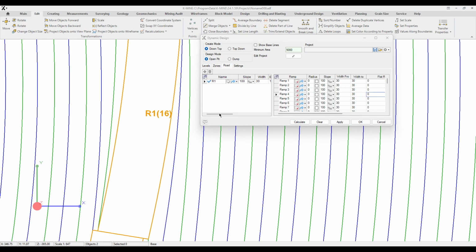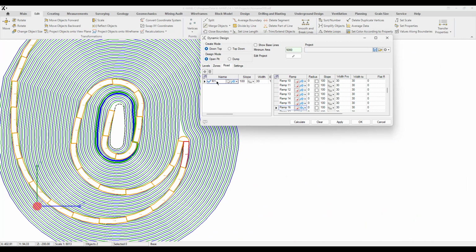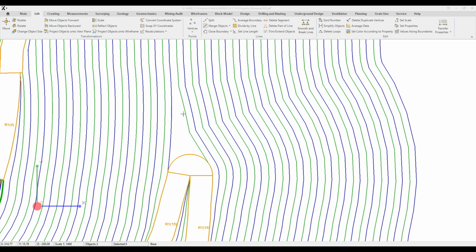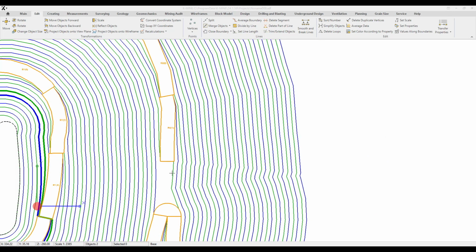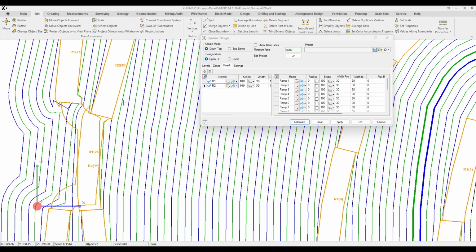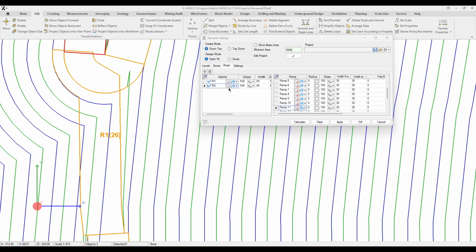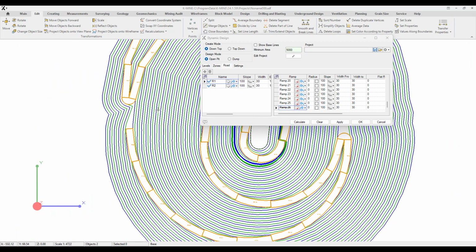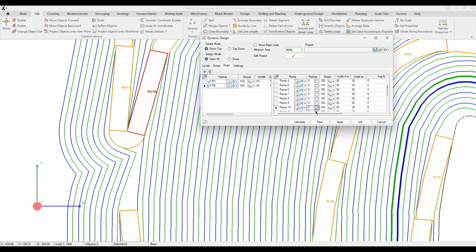Moreover, at each step of the design, you'll have prompts in the form of highlighted elements, such as individual ramps, the entire level, added baselines, or specific zones. With a focus on road construction, the settings are as flexible as possible at all stages. If one road overlaps with another, we have to make a decision on what to do next. We can stop the progression of one of the roads, add a switchback to the other road, stop both roads, create a third road or two switchbacks. Or, the choice will ultimately depend on your specific needs under given conditions.